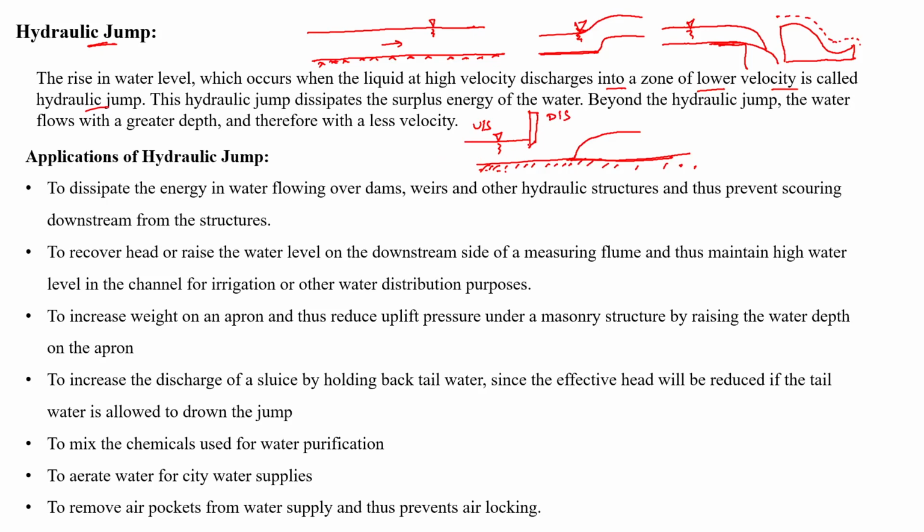When you push the sluice gate down, what will happen? The flow tends to rush, and after a certain distance from the gate on the downstream side, the depth will increase. Why? Because when you apply a force like a sluice gate in the flow direction, the flow changes from high depth to low depth. Here it is y1, here it is y2, so y1 is greater than y2.